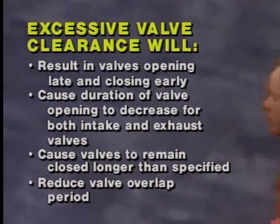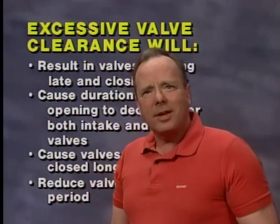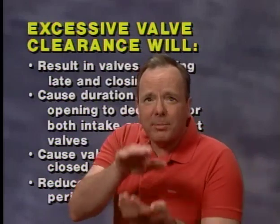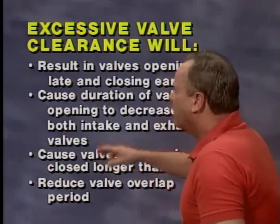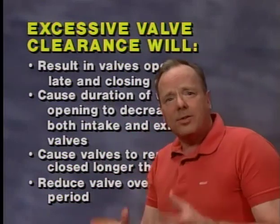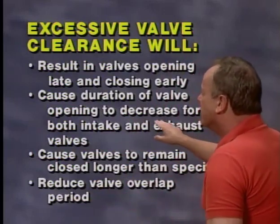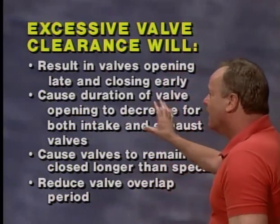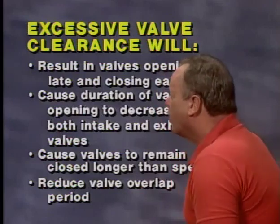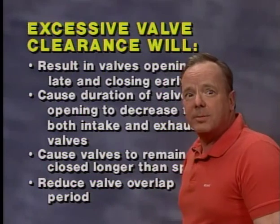Now let's assume that you adjust the valves on an engine and you have too much clearance. Well, that's a bad thing because there'll be too much play in the valves, and what's going to happen is you have to take up that play before anything happens. So that's going to result in the valves opening late and closing early. And that tells you right then that the valve isn't going to be open as much, so it's going to cause the duration of valve opening to decrease. It's going to happen for both the intake and exhaust valves. So the valves are going to be open less, and therefore they're going to be closed more. So the valves will remain closed longer than maybe specified by the engine manufacturer.